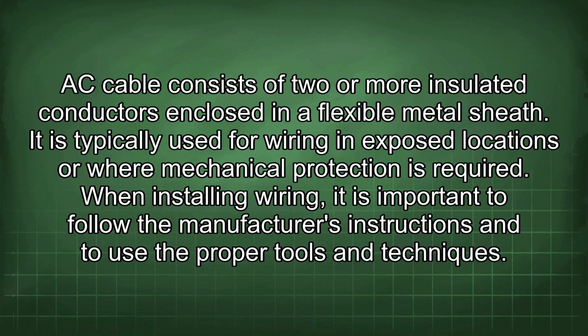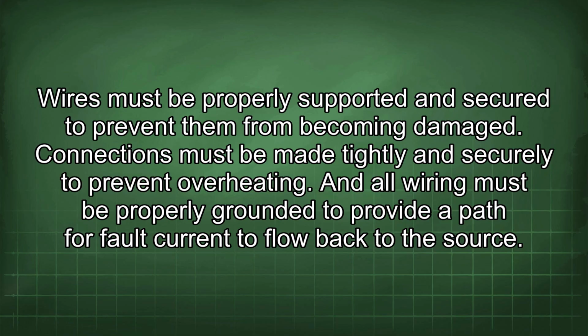When installing wiring, it is important to follow the manufacturer's instructions and to use the proper tools and techniques. Wires must be properly supported and secured to prevent them from becoming damaged. Connections must be made tightly and securely to prevent overheating. And all wiring must be properly grounded to provide a path for fault current to flow back to the source.